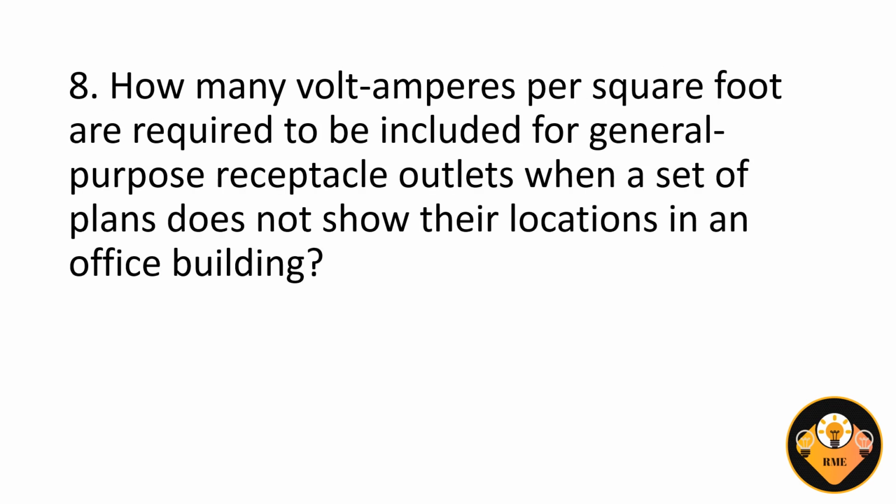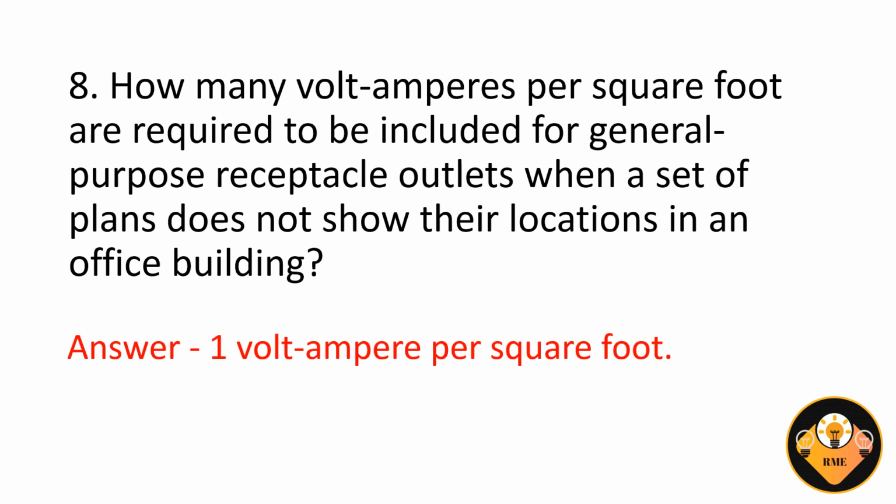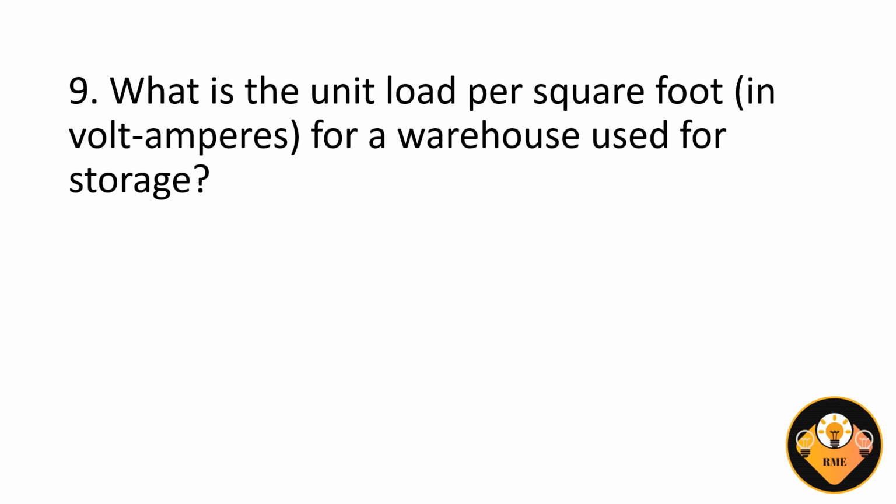Number 8. How many volt-amperes per square foot are required to be included for general-purpose receptacle outlets when a set of plans does not show their locations in an office building? The answer is 1 volt-ampere per square foot. Number 9. What is the unit load per square foot, in volt-amperes, for a warehouse used for storage? The answer is 1/4 volt-ampere.